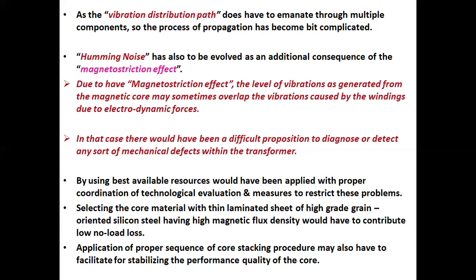Selecting the core material with thin laminated sheet of high-grade grain-oriented silicon steel having high magnetic flux density would contribute to low no-load loss. Application of a proper sequence of core stacking procedure may also facilitate stabilizing the performance quality of the core.